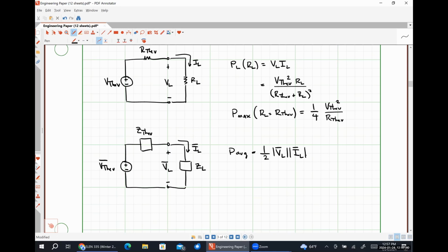So that's just the magnitude of our phasor current IL, times the cosine of theta V minus theta I. So this expression right here is literally just the average power relationship that we came up with about 20 minutes ago. I'm just expressing it in very slightly different terms to tie everything back to the phasor quantities in our circuit that we're looking at, okay?